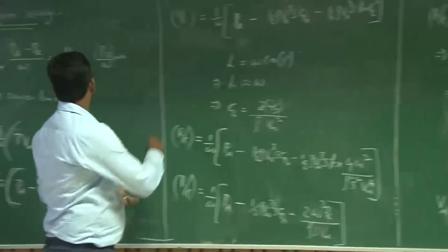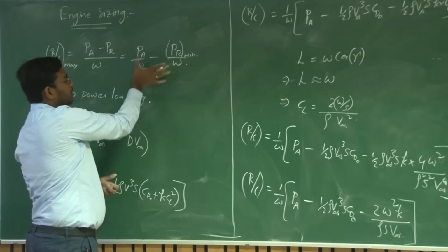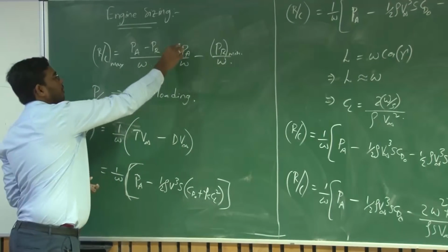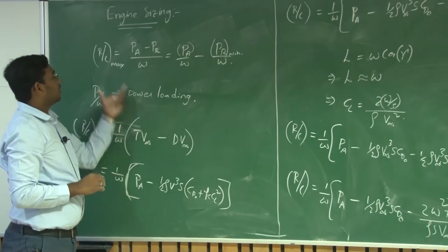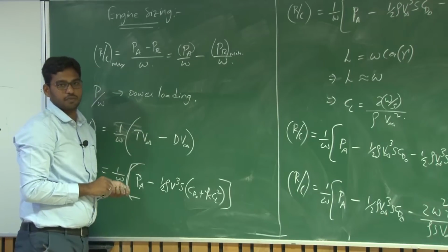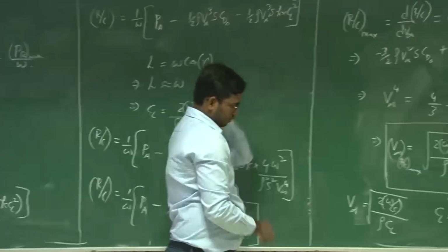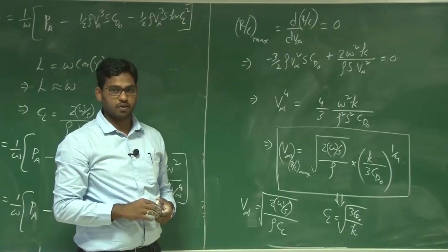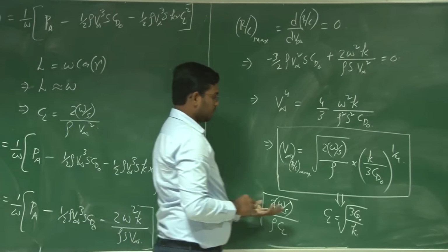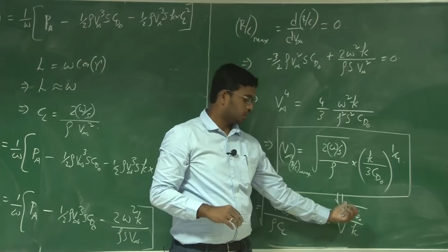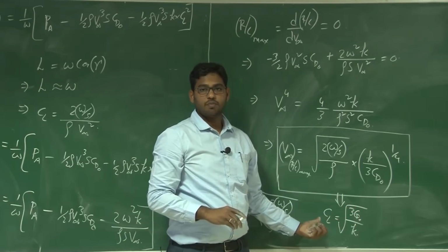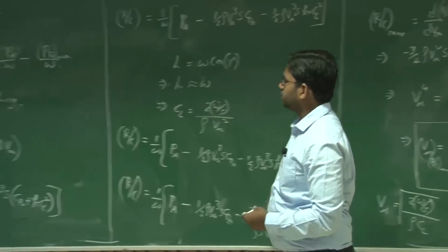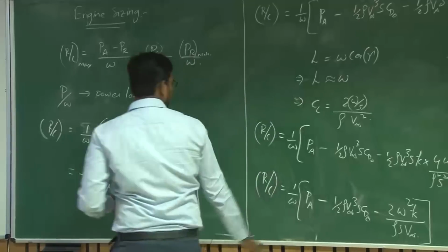So, if you fly at minimum power requirement, this particular quantity is less, and we have higher specific excess power from a given power plant. That means if you are operating at the maximum power, you will have the corresponding maximum rate of climb. So, this condition corresponds to CL power 3 by 2 by CD maximum, right. When you do CL power 3 by 2 by CD max, the corresponding CL value is root over 3 CD naught by K, which is the minimum power requirement condition in a level flight. So, why both are same, rate of climb maximum and minimum power requirement.